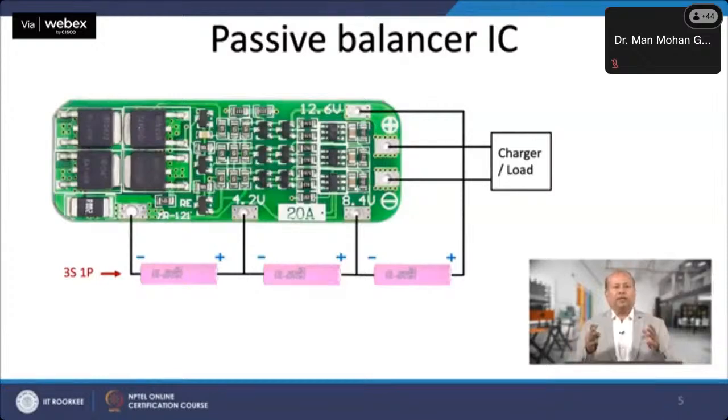It can handle 20 ampere of current and has protection for short circuit, overload, discharge and overcharge, which provide safety and protection for the lithium ion batteries. A DC power supply is used to charge the battery and a rheostat of 20 ohms for discharging operations.